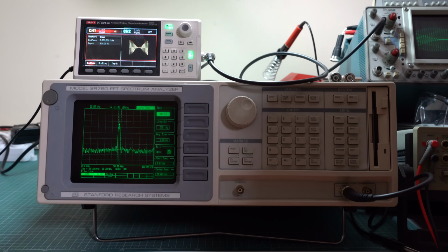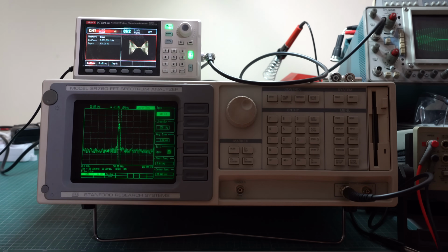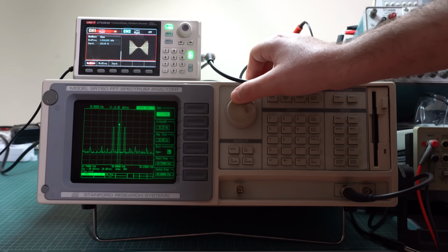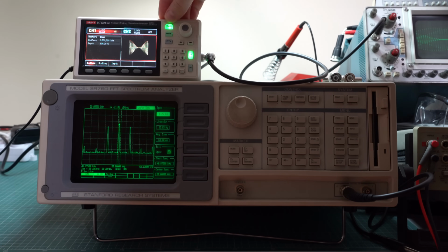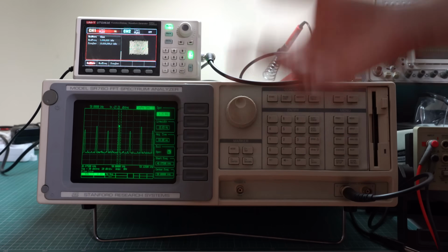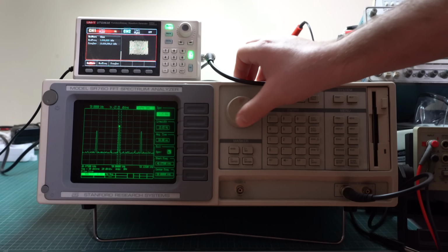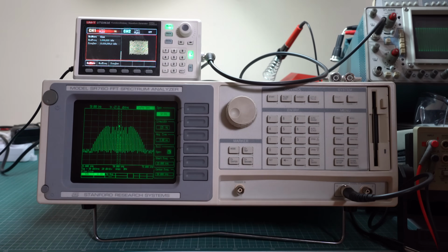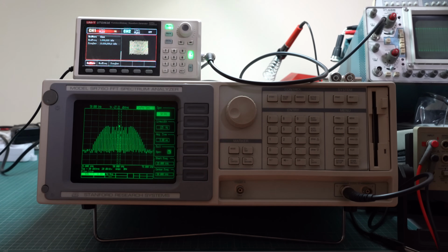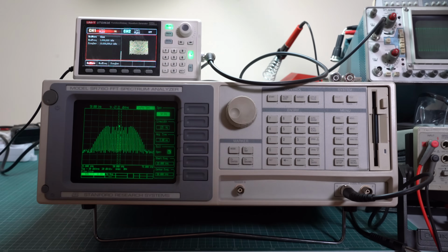Similarly, a spectrum analyzer can also be used for checking a modulator. So you can check the main modulation parameters like modulation depth for AM or frequency deviation for FM, and this can be easily demonstrated. For example, here's an AM signal, and you can clearly see the modulation here, and you can also switch the generator to FM, and in this case here's what an FM signal looks like. This can be characterized by the spectrum analyzer once again to make sure that the modulator works right before connecting it to a transmitter and an antenna.